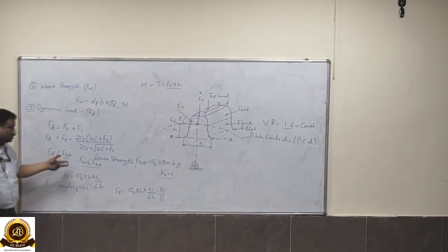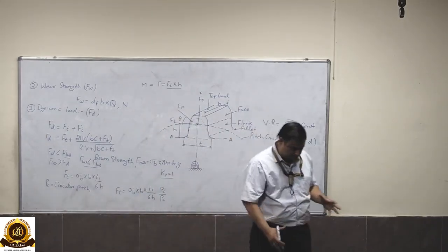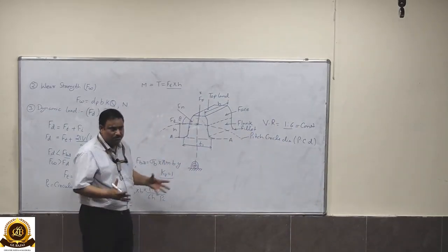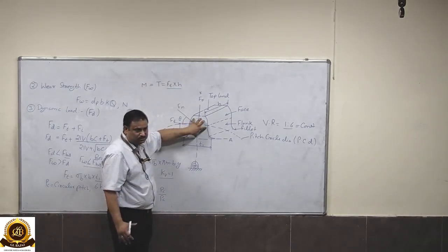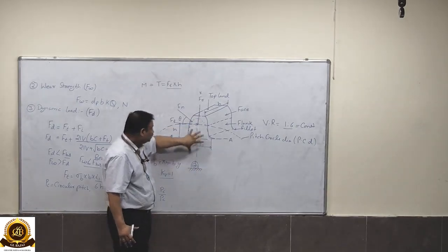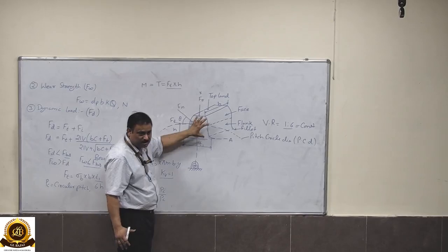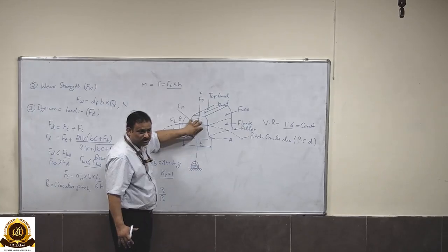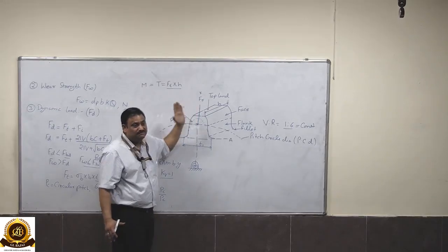So in order to check the surface hardness, why do we provide the surface hardness? Because sometimes we want to reduce the cost of the gear. We use the composite gear. Composite gears means we have to use the hardened material on the surface of the tooth, whereas the softer material can be used for the rim. Okay, so we can use here the hardening process like flame hardening or carburizing process to harden the surface only. The inside is soft, where the surface is hardened, and it will increase the wear strength.